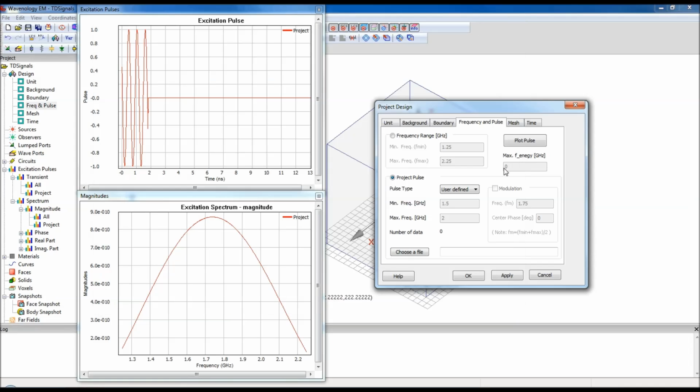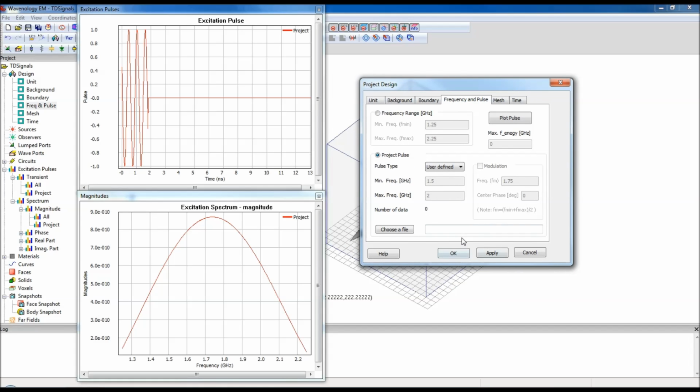Now, what I want to emphasize here is the user doesn't have to worry about their time steps exactly matching the delta t that is going to be used in the simulation. For example, at t equal to 0, your signal is 0, and then at t equal to 1 nanosecond, your signal is 5. Then you can input another data point at t equal to 5 nanoseconds. For example, your magnitude is -1 or whatever. So you see that the delta t doesn't have to be canonical, doesn't have to be identical.